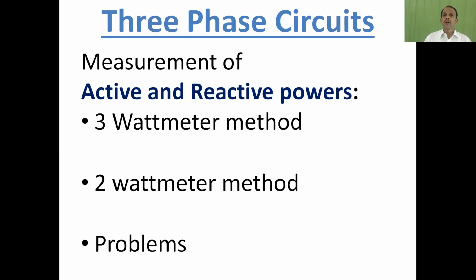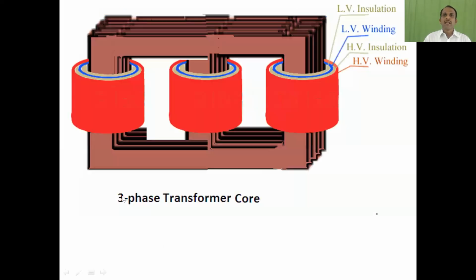We can find out phi, the phase difference between voltage and current in a three-phase system. By that, we can find the cos factor, which is cos phi, which is nothing but the power factor of this system as a whole. So we mostly measure the power by the 2-wattmeter method. And these are the basic applications of the three-phase system.